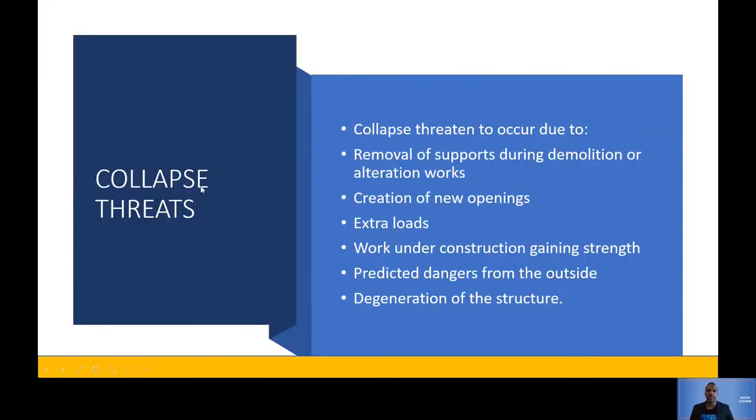Let's go on. Now let's talk about the threats that are involved with shoring. Remember, collapse is the major threat, but we need to know what causes collapse of these shores. First, removal of supports during demolition or alteration works.